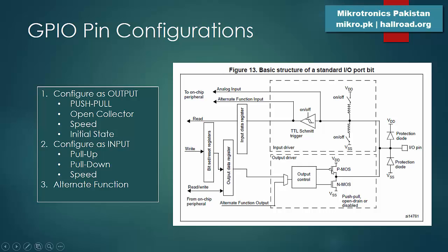Or we can connect it only as an open drain. In open drain, this transistor will not be functional, only this transistor will be functional. So the pin can either be only 0 or in an open state when we set it to high logic or 1.